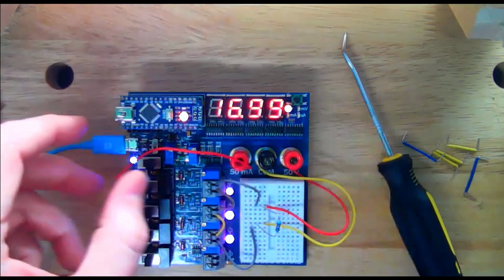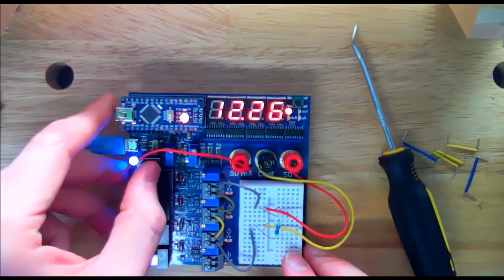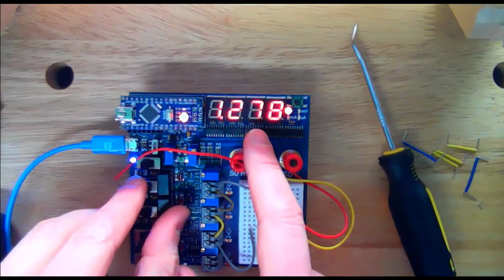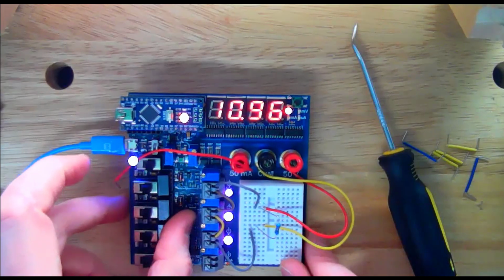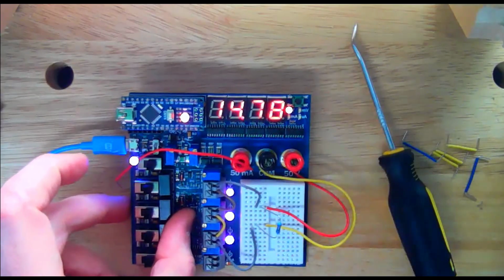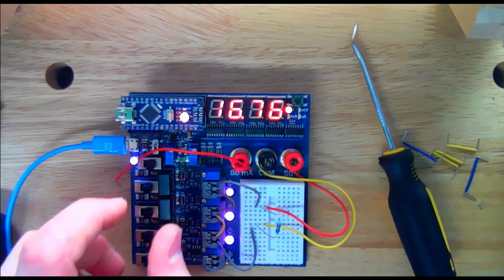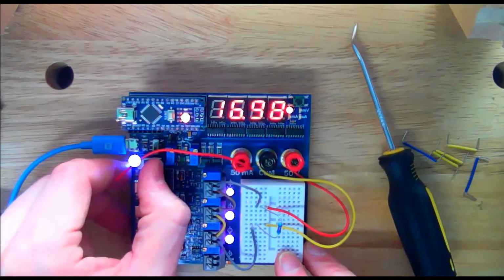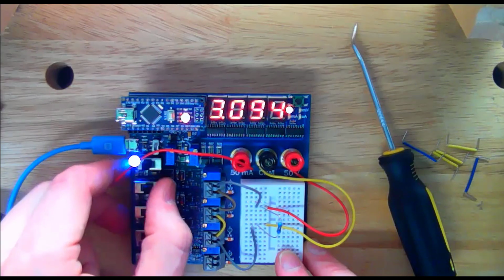Some other things. So let's de-energize this. So that's the high resolution, low resolution. De-energizing the board here. Now notice how slow that drops. So when we're in high resolution, I'm going to turn it back on. When we're in high resolution, look at how long it takes for that voltage to creep up to its proper value. That's the downside of averaging over a lot of samples to get a nice smooth value, is it moves slow. So when we turn this board off, look at how slow that number drops.